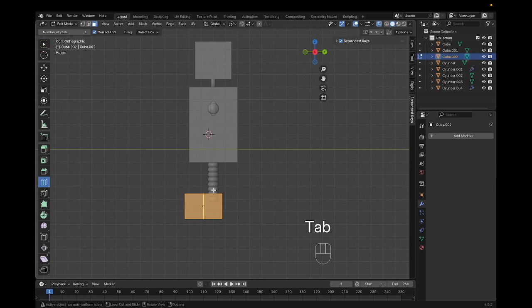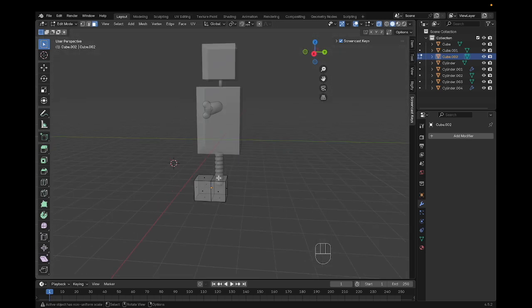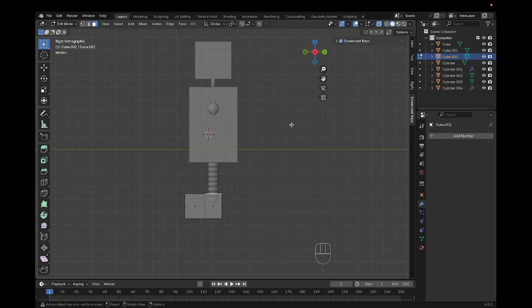Loop cuts automatically go halfway, or at thirds if it's at 2. But anyway, you're here and we're going to select it, and now if you hold down, you can move the loop cut. So position it where you want the boot to go up. Now we're going to go here. If you're in face select mode, turn off X-ray. Actually, we'll keep it on for this. Select this tiny little black dot here for that face. Go back into X, and we're just going to extrude it up a little bit.